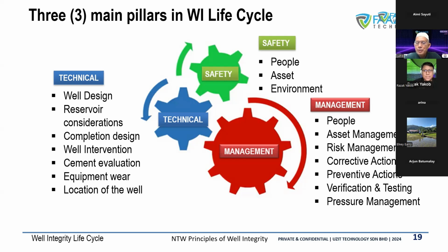Some companies will consider that cemented casing is not a barrier because we have open hole down there. So it's subject to condition. But for us, for the safety of the people and for the hazard, I will consider tested cemented casing as a barrier, because the formation at the bottom is another area of concern. So we are concerned about the casing and upwards, where we have the properties, the asset, and the people. Of course, managing this problem at the bottom in open hole can depend. It depends on so many things, like for example, we have well control, uncontrolled blowout.